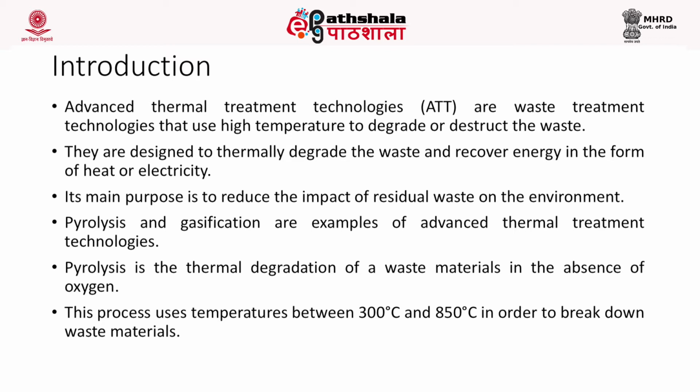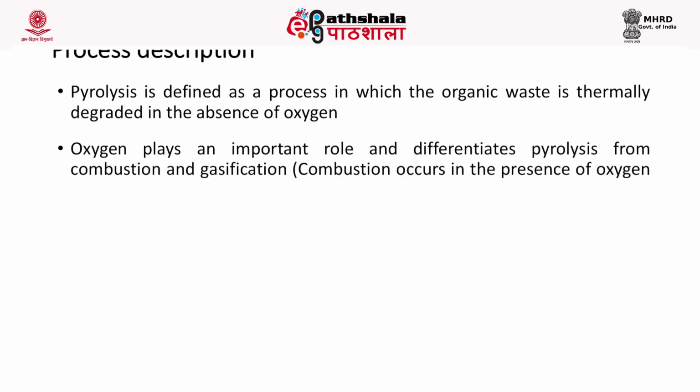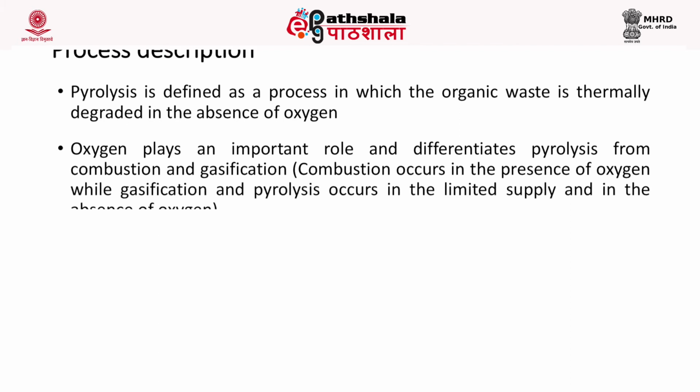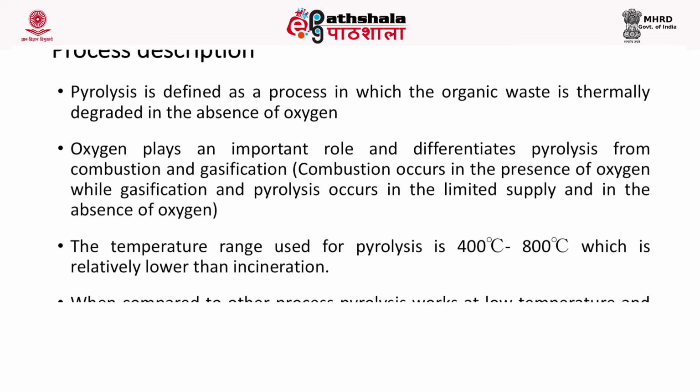Pyrolysis is a thermal degradation method where the waste is destructed or degraded in the absence of oxygen. That is nothing but burning the waste in the absence of oxygen at a very high temperature of 300 or 350 to 850 degrees Celsius. Now, the process description. Pyrolysis is defined as a process in which the organic waste is thermally degraded in the absence of oxygen. Oxygen plays an important role and it differentiates pyrolysis from combustion and gasification.